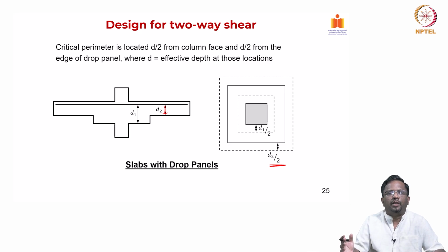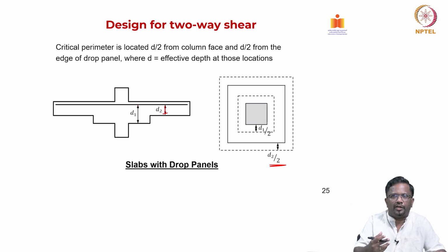As I said, in flat plate structures, punching shear stress can be quite high, particularly in the edge columns and corner columns, because you have to transfer a lot of unbalanced moment at those regions. Typically, you may not satisfy the limits, then you have to go for locally thickening and putting a drop panel and so on, so that it is not going to be a concern for two-way shear.